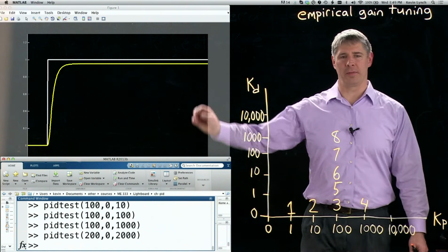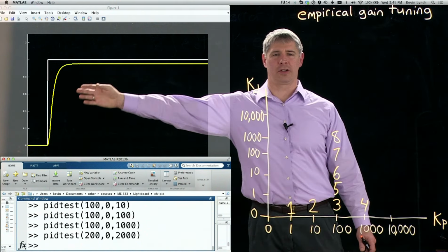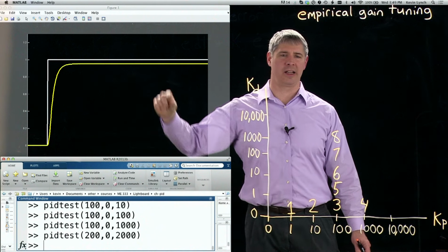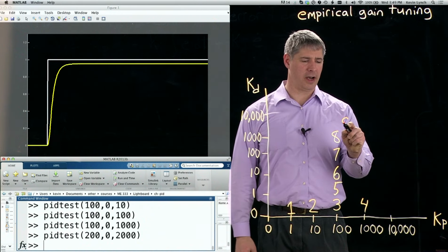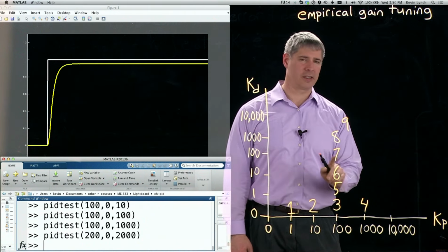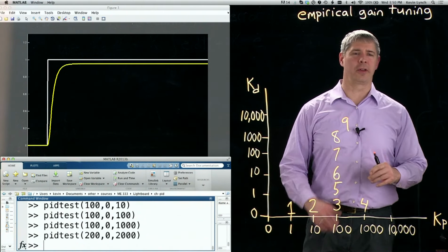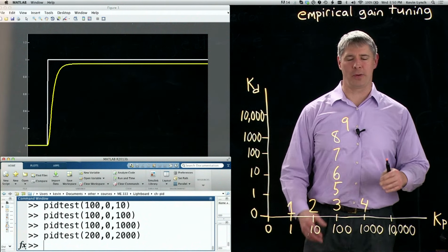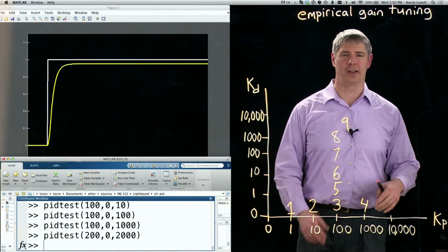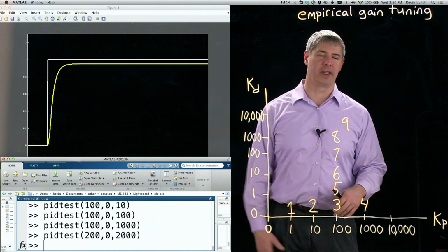Okay, now I'm getting even better performance. Still the good transient response, less steady state error. So this is guess number 9. We've increased in both K sub P and K sub D. So let's stop there with our PD gain tuning. And by the way, we can't make our gains arbitrarily high or else we're going to see chattering behavior.